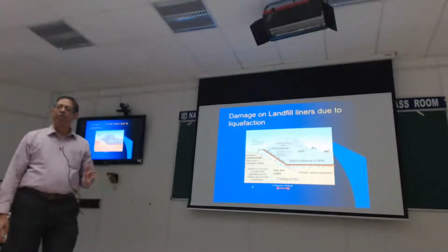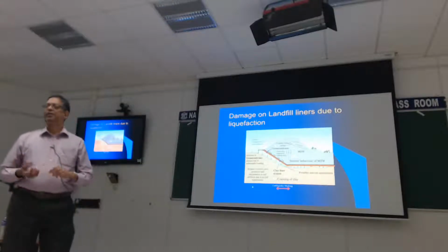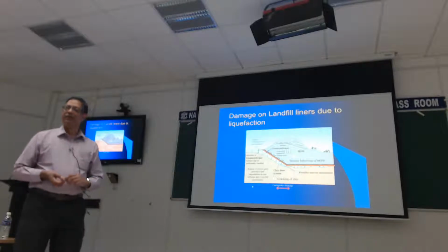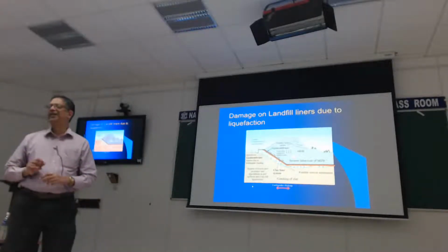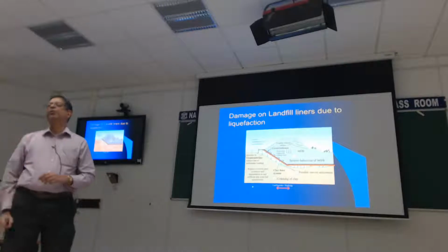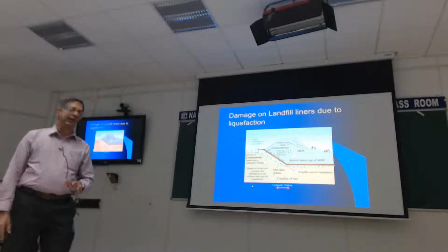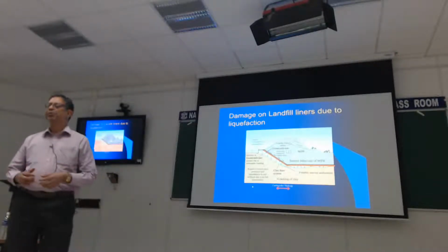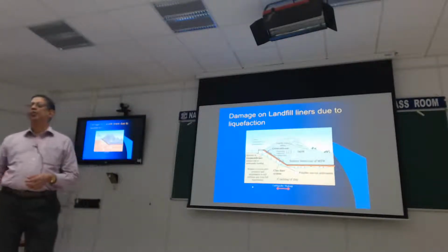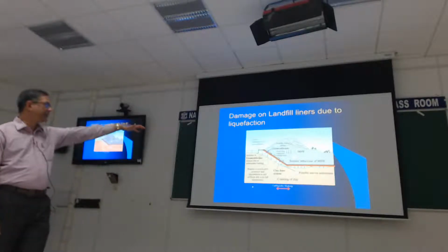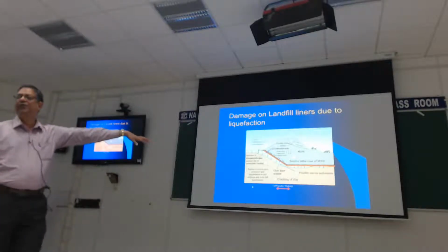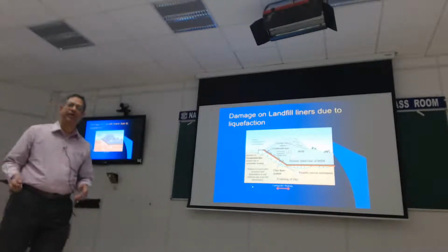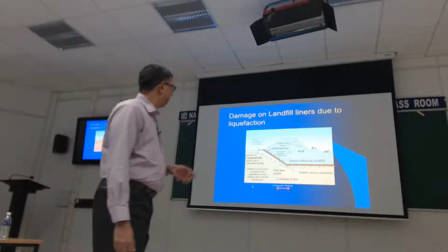Now, in most countries, it's illegal to have waste in landfills unless the landfill has at least 2 layers of protection. Because we all recognize once you put all the municipal solid waste in one location, it produces, due to chemical reactions, what's called leachate, and all the leachate will come to the ground, to the base. And if you don't have liners, it will go into the groundwater. It seeps, mixes with groundwater, and people will fall ill.